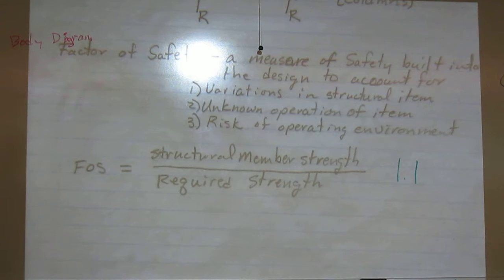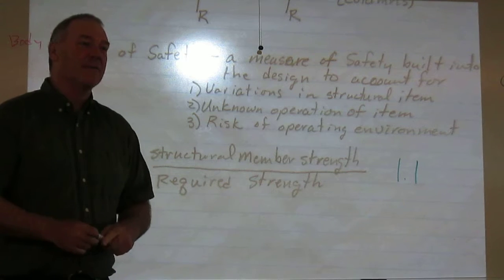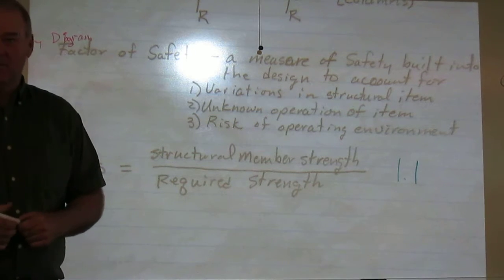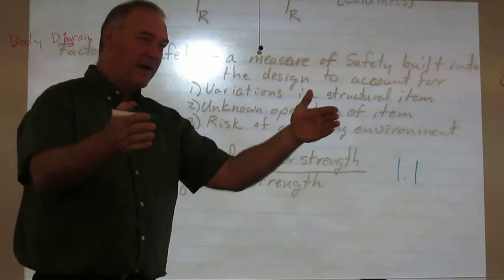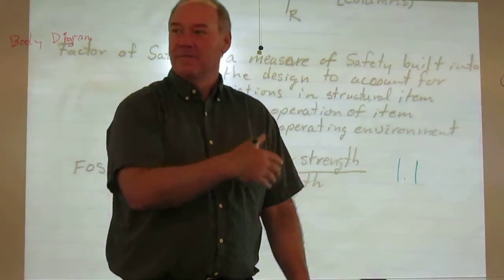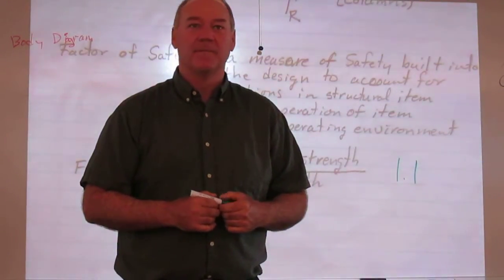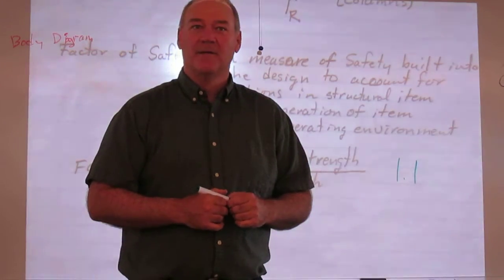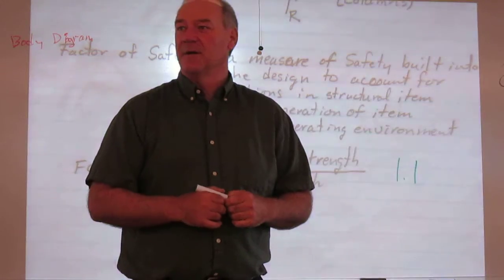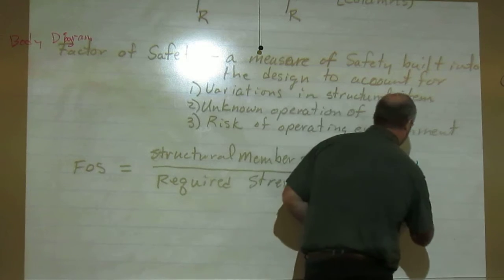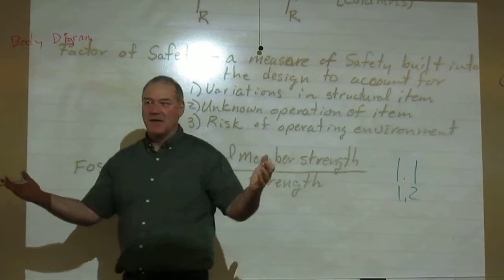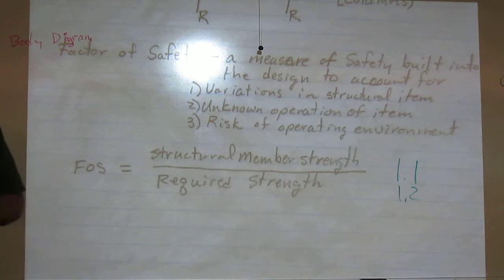When I was mining, we did all of our slopes. I was an open pit miner. All of our slopes were generally designed at a factor of safety of 1.2 because we wanted them to fail. Right? We wanted to go in, we wanted to mine something. When we pulled out, we hoped the whole slope fell in so that we didn't have to reclaim it. It naturally reclaimed itself. Okay, so that was a 1.2 that we used on all of our pit walls. And we knew at a 1.2 that we would get small landslides all the time. And it's just cheaper for us to mitigate those small ones in the hopes that we get a big one when we're done and save us millions in refixing that pit.